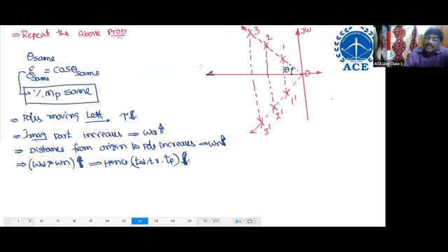Because horizontally it is more stable, vertically less stable, and diagonally the same relative stability. That's all. You try to draw the response by yourself. You have to draw the response such that all should have the same peak overshoot. Okay? So more angle, more relatively stable. Less angle, less relatively stable. Remember, all having the same angle means the same relative stability.